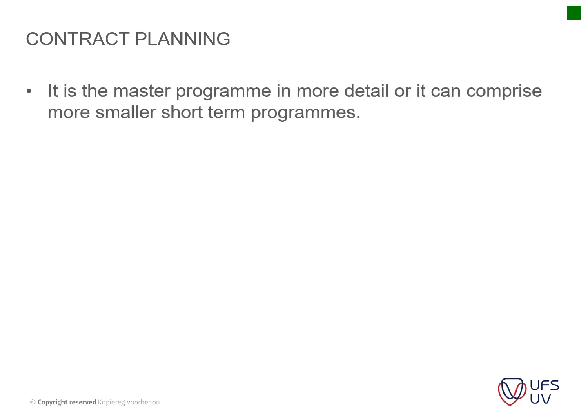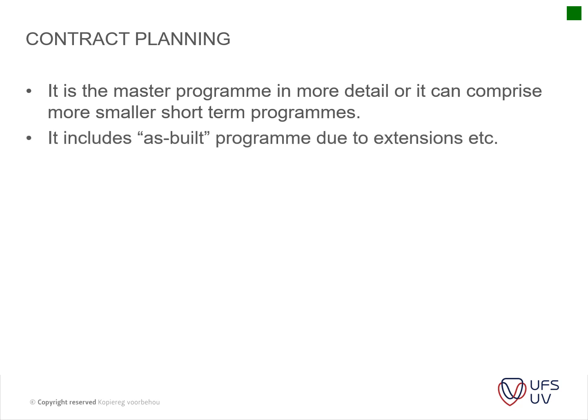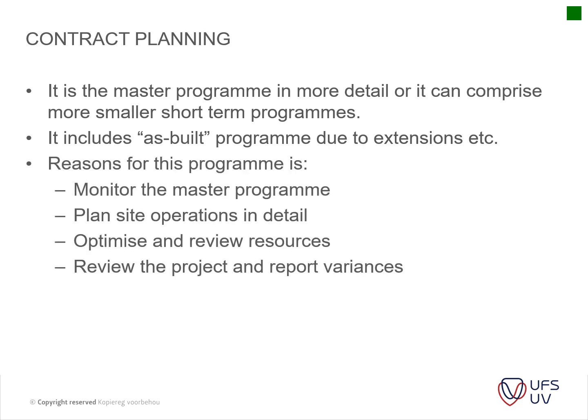Then your contract planning. This is now your actual contract when you start. It's a master program in more detail, or it can be compressed into smaller short-term programs. It includes your as-built program due to extensions, etc. The reasons for this program are to monitor the master program, plan site operations, optimize and review your resources, and review the project and report variances. So it's basically for control.